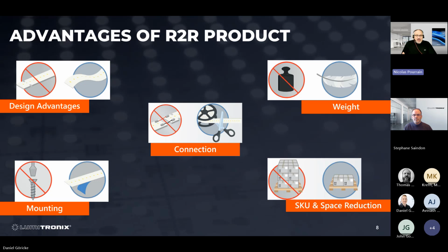One part number can replace several different rigid PCB sizes and also handle the possible uniformity issue in brightness with different lengths of PCB connected to the same driver, as in this manufacturing process we guarantee that only one LED reel is going to be populated on one LED flex reel on the output, which is unique.